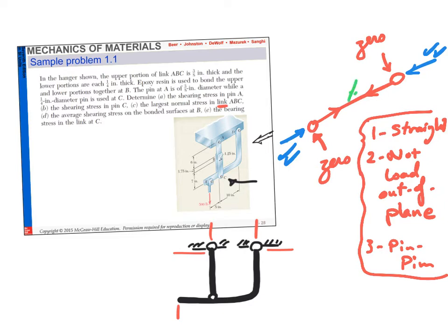loading out of plane. You see what out of plane means? Any loading that is like this. If I don't have those, this applies. There is zero out of plane force. Is that easy? Can you remember trusses? You guys took some trusses in statics. What makes the truss uniaxial? You cannot say that the force in a truss member has X and Y components. There are only axial forces, huh?